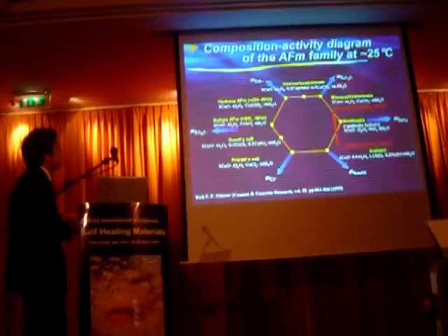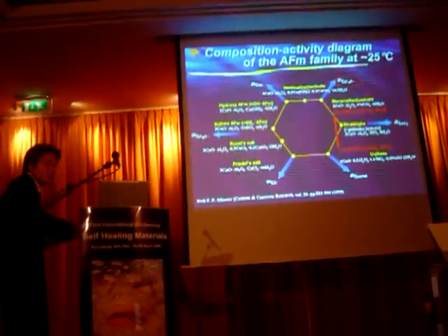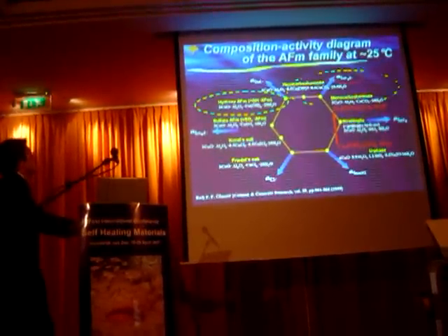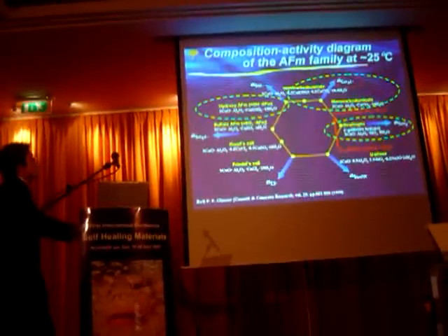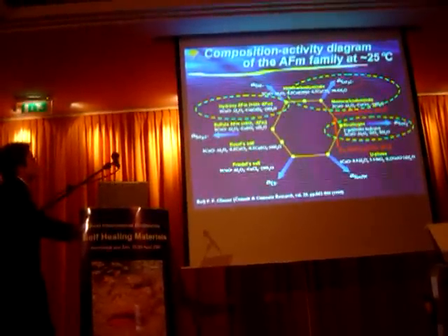So from this result, we guess that rehydration products such as hydroxy AFm, hemicarbonate aluminate, monocarbonate aluminate and ettringite are very desirable for self-healing design in civil infrastructure.